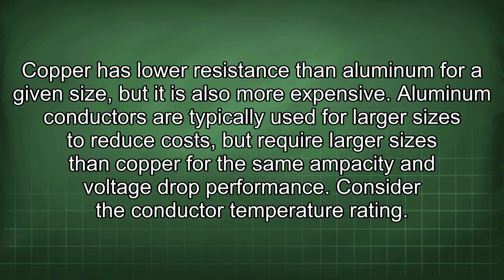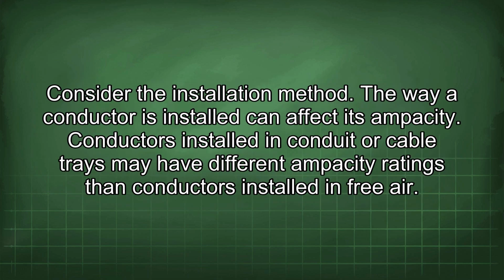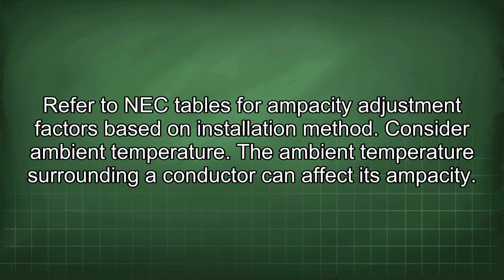Consider the conductor temperature rating. Conductors are rated for specific operating temperatures. Ensure the selected conductor's temperature rating is suitable for the application and installation environment. Higher temperature ratings allow for higher ampacity, but may also require special terminations. Consider the installation method. The way a conductor is installed can affect its ampacity. Conductors installed in conduit or cable trays may have different ampacity ratings than conductors installed in free air. Refer to NEC tables for ampacity adjustment factors based on installation method.